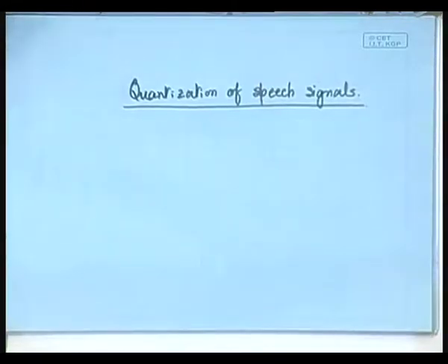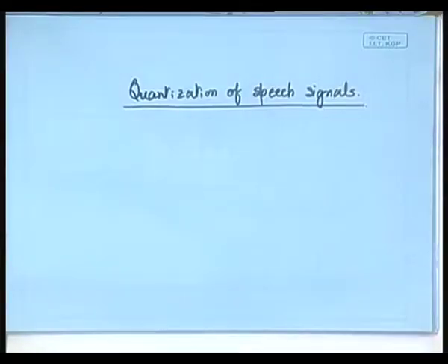Now, whenever we would like to have any waveform approximation coding, or even for parametric coding, one of the essential steps that we require to store and process the digital samples is quantization. Before quantization, of course, we require sampling of the speech signal.